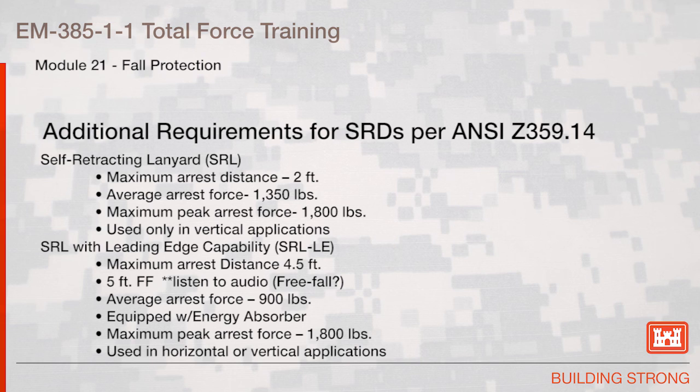SRL with leading edge capability, SRL-LE. Maximum arrest distance 4.5 feet. 5-foot free fall distance. Average arrest force 900 pounds. They are equipped with an energy absorber. The maximum peak arrest force 1,800 pounds.